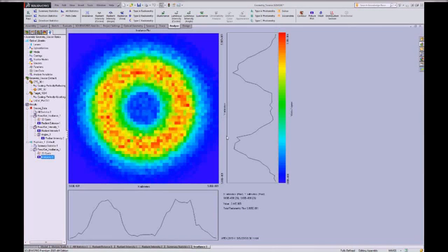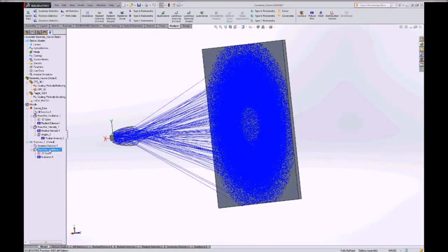But I can also look at an irradiance projection in a false color plot. Now, we do see that this is statistically a little bit noisy. I'm not going to spend time tracing a sufficient number of rays because I only have a small amount of your time this morning. But what I can do, for example, is choose this irradiance information, and I can do a little bit of statistical averaging.